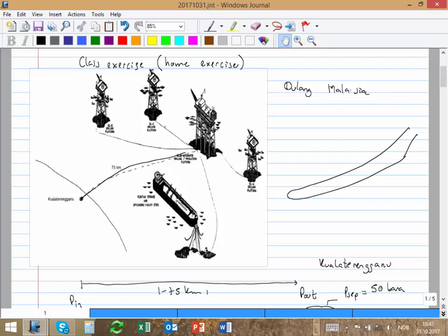Or I can give you another pipe with a heat transfer coefficient of 1.5. That is going to save dramatically. It's going to reduce the appearance of wax in the line, etc. Basically, it's the type of insulation, the quality of the material, and also its thickness.